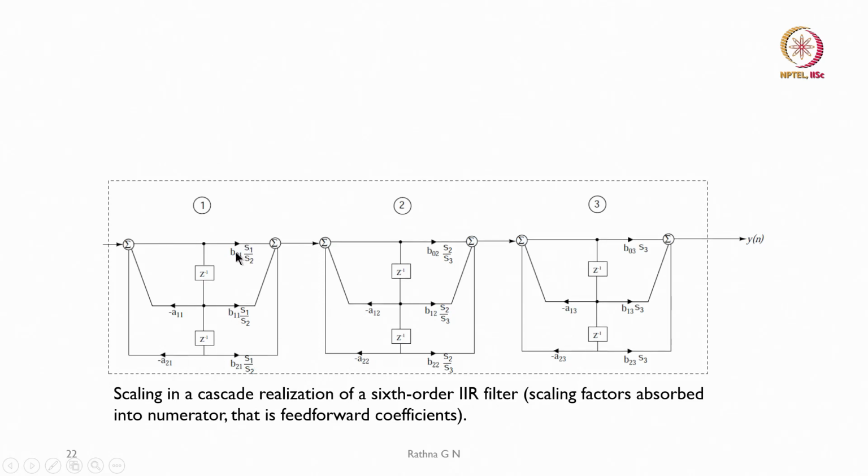One way is to do the division when you are storing, after multiplication and before summation. You can scale them and then do the addition. That way you avoid overflow, instead of adding them, getting an overflow, and then dividing later. So, you can provide the scaling factor right there.